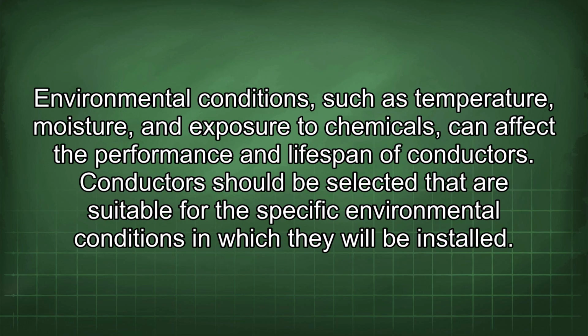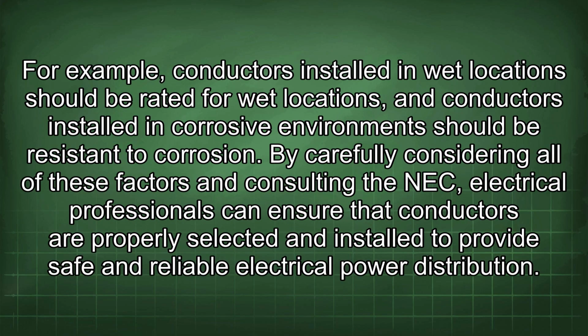Environmental conditions such as temperature, moisture, and exposure to chemicals can affect the performance and lifespan of conductors. Conductors should be selected that are suitable for the specific environmental conditions in which they will be installed. For example, conductors installed in wet locations should be rated for wet locations, and conductors installed in corrosive environments should be resistant to corrosion. By carefully considering all of these factors and consulting the NEC, electrical professionals can ensure that conductors are properly selected and installed to provide safe and reliable electrical power distribution.